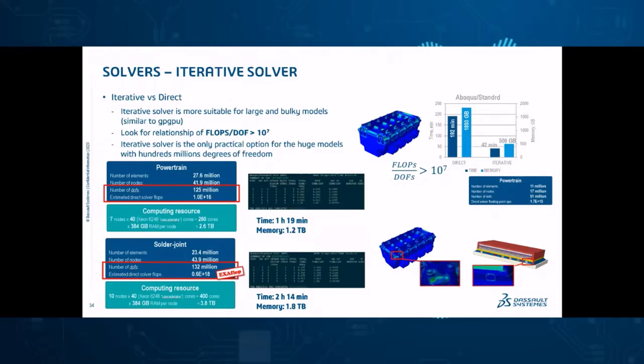And secondly, we've been continually developing the iterative solver over the last few releases to make it more usable for a broader array of models. For example, with improved preconditioners for models with Lagrange multipliers, there's an unsymmetric version of the iterative solver. So maybe what didn't work for you a few releases ago may work now, and we'd encourage you to try the newer implementation.